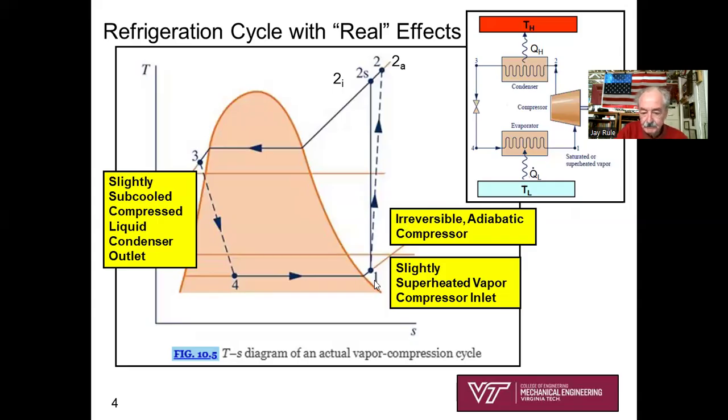Now here's another one: what goes into the compressor inlet would sometimes be considered slightly superheated vapor. In other words, the heat that's going into the refrigerant in the evaporator is enough energy to make state one go a little hotter than saturated vapor. And so this sketch does a nice job in communicating. Notice how it's not greatly superheated. I'm calling it slightly superheated.